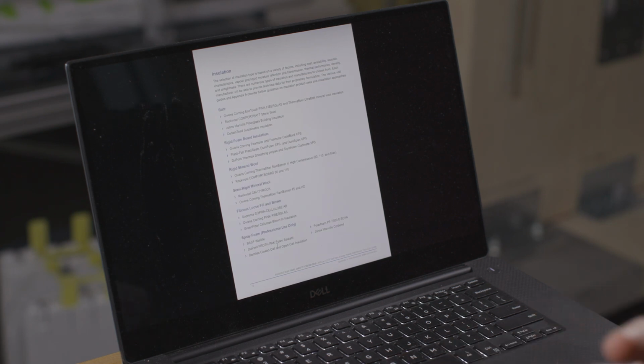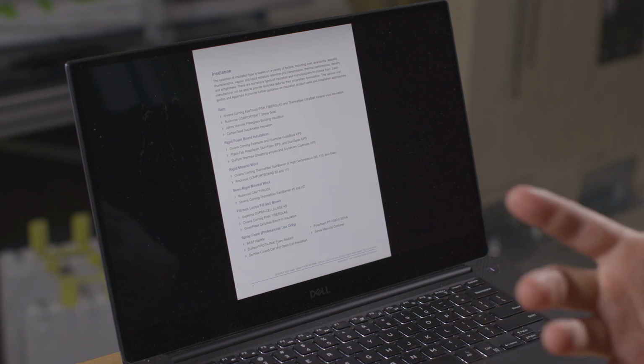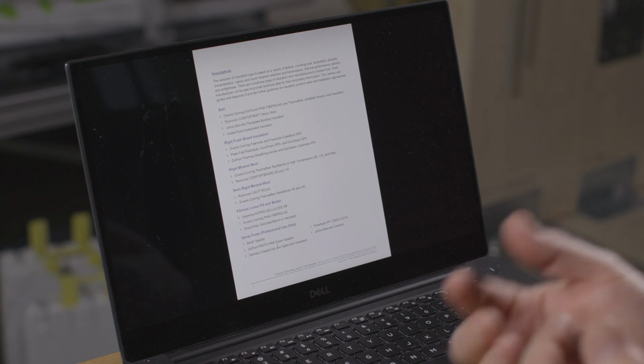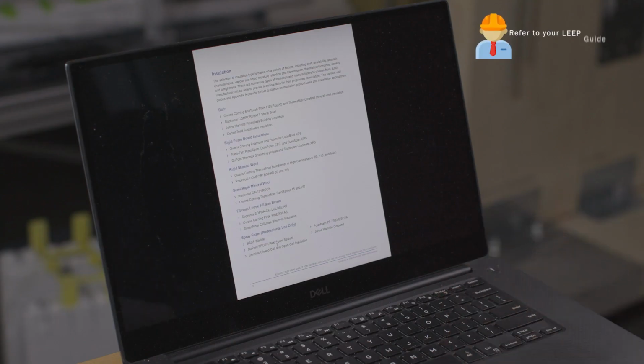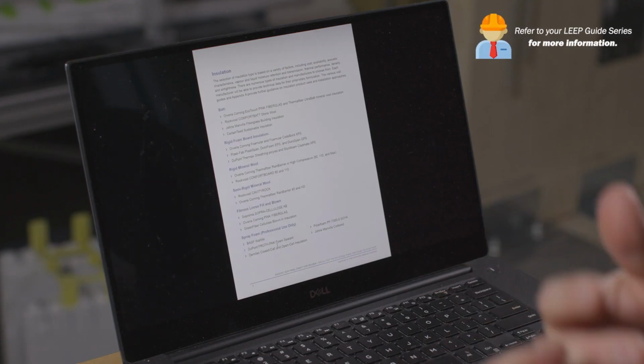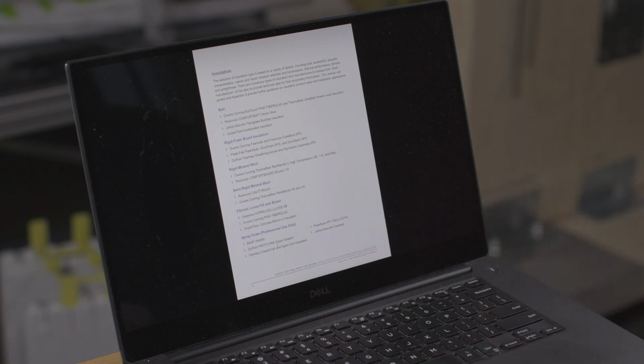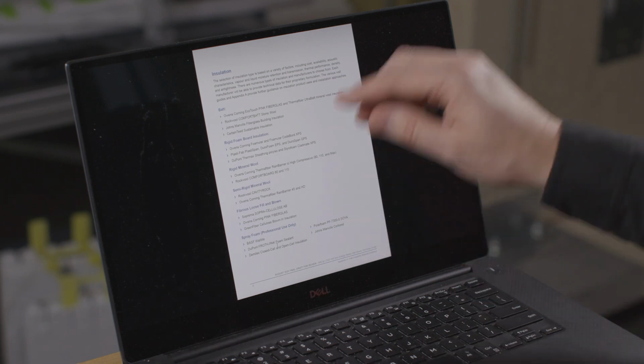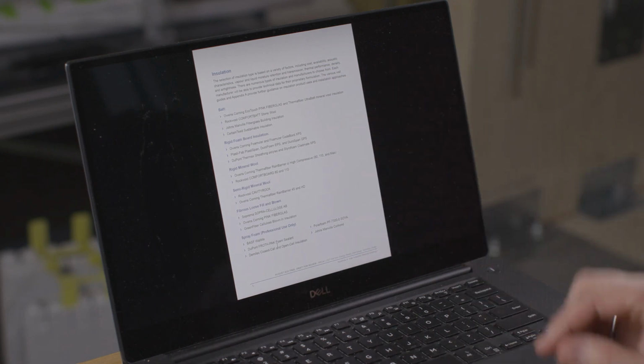Insulation. In the other videos, we talked about the different types of insulation. We've got batts, we've got rigid boards. In the rigid boards, we've got XPS, EPS, rigid mineral wool, and semi-rigid mineral wool, which is a softer density than the rigid. We've got fibrous loose blown, so things like cellulose and blown-in fiberglass. And then we have spray foam. Spray foam is typically installed by professionals. These are usually two-component spray foams, closed cell or open cell. Again, some starting points there for suppliers in Canada that can help you out.